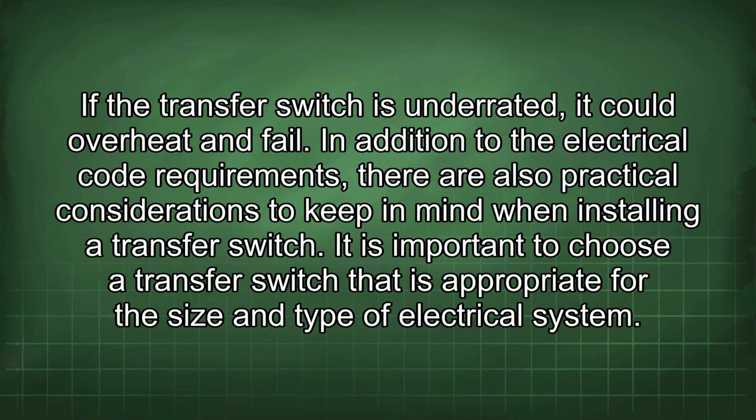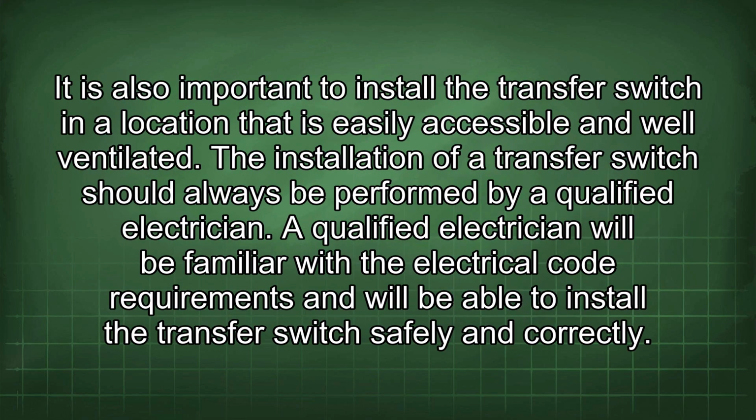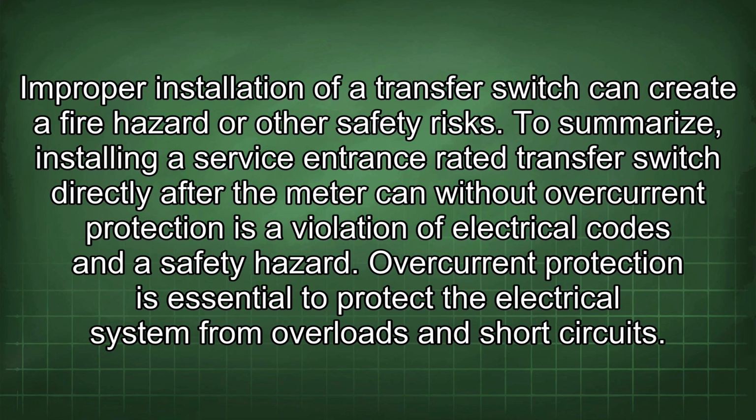It is important to choose a transfer switch that is appropriate for the size and type of electrical system. It is also important to install the transfer switch in a location that is easily accessible and well ventilated. The installation of a transfer switch should always be performed by a qualified electrician. A qualified electrician will be familiar with the electrical code requirements and will be able to install the transfer switch safely and correctly. Improper installation of a transfer switch can create a fire hazard or other safety risks.